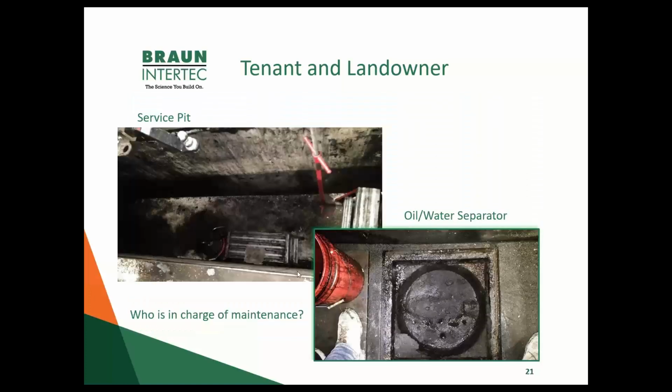We also found in the service pit at the repair shop an oil water separator, which drains to the sanitary sewer system, but has clearly not been serviced in the entire 7 years that the tenant has been in operation. So clearly there was some miscommunication as far as who was responsible for maintaining that, and that it did need to be maintained. What happened here is the bank actually refused to let the landowner use this property as collateral. So it can be some big issues if that communication and that compliance isn't maintained.